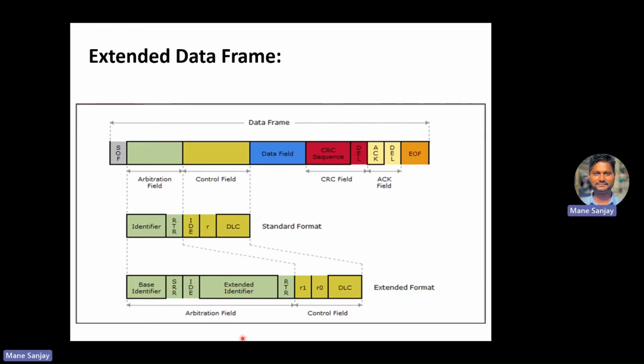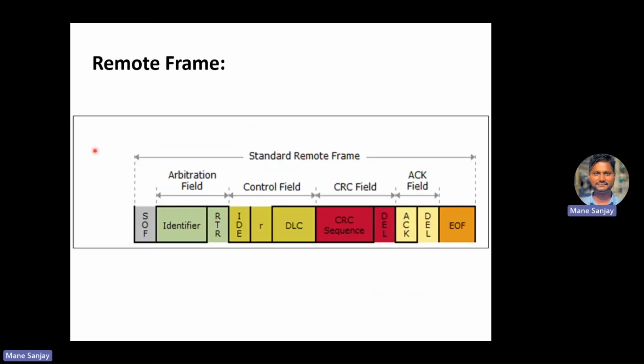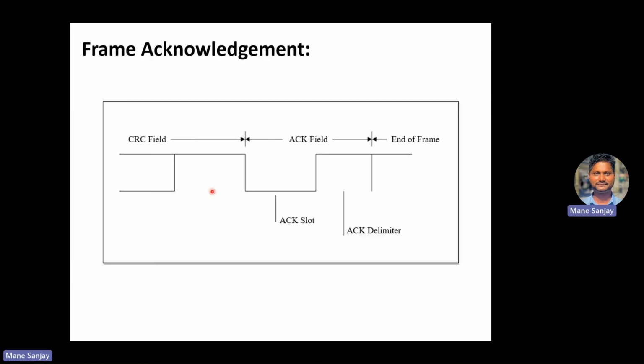So moving to the next, till now we have covered something very important, that is the CAN frame. So let's jump to the next, that is the remote frame. I explained earlier that the remote frame is used when some ECU wants to request some information, so it only sends the identifier. Here you see the identifier field is there. RTR is 1, earlier it was 0. These are reserved and the DLC. Here it should definitely be 0, but if you set something over there, it doesn't care. The data field is not there. Data field is 0. It decodes that the next bits are the CRC sequence, so it calculates the cyclic redundancy check for error handling. So this is how the remote frame works, request-based communication.